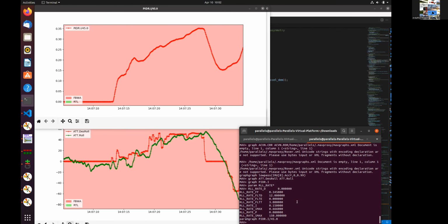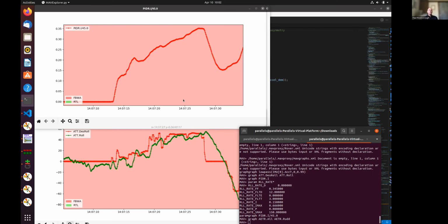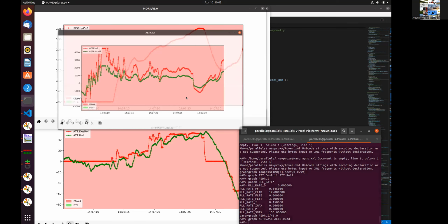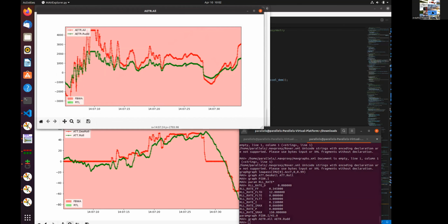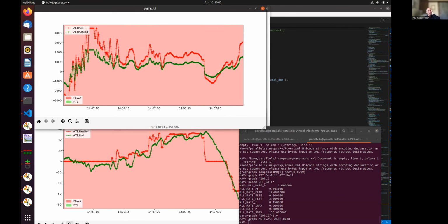Or lower the IMAX, but is this particularly prone because it's a V-tail? With the V-tail, the rolling effect from the tail is in the opposite direction to the yaw effect. Well, if I graph AETR, you actually get the tail competing with the ailerons in a V-tail. Yeah, there was mixing going on, they did have rudder mixing, you can see. So yes, it was an unhappy airplane.